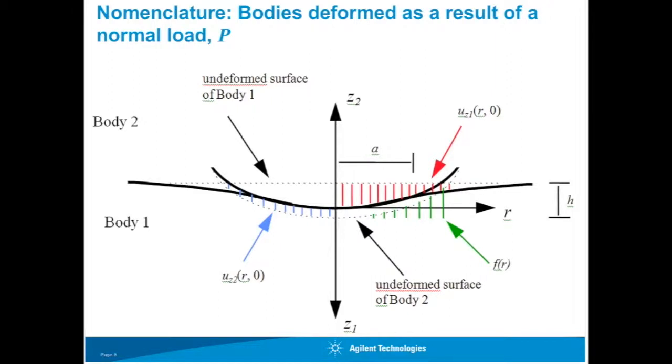Rita, I have a question that came in on the chat. You said that it's questionable to use this equation for sharp indenters. What is the form used for Berkovich indenter? It's not questionable. It's always used for sharp indenters. It's just cleverly applied to the unloading curve, which is a purely elastic curve. So you have to be clever about how you're applying it, and that's actually the focus of Benoit's presentation. But the use is not particularly questionable. It's very common.